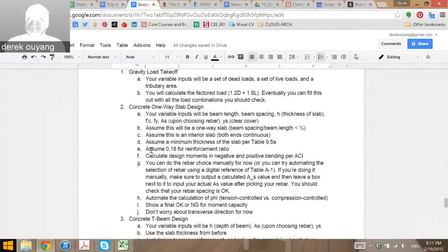Also keep in mind one big difference between concrete and steel: when you design a steel girder, you find the maximum moment anywhere in the section, and you design the whole section to that maximum because you just have a shape, right? Whereas with concrete, you can change the flexural capacity of the section all throughout it by changing your rebar spacing. So it's actually a more economical design, but you just got to do more checks. Don't worry about that for now, but just know that, of course, that's something you have to do in concrete design. You change the rebar from top to bottom as you go over the supports and things like that. But just in your mind, concrete has that advantage over steel because you can be very economical with where your rebar is acting. But for now, just assume you're always designing this simple condition.